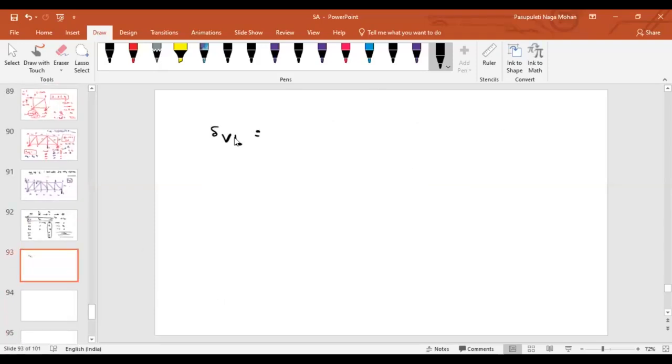It is the unit force in member BC due to unit load times the fabrication error in BC. Except these two, all other values are 0. Is it clear now? Now this value is given directly as minus 3.